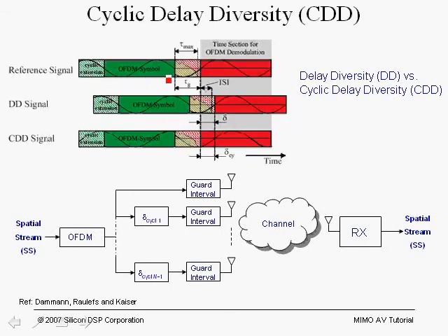Basically we're showing two OFDM symbols, one in green and one in red. In the case of OFDM we have the cyclic prefix, which in the case of 802.11a is 800 nanoseconds, or a copy of 16 samples at 20 megahertz of the OFDM symbol that is then prefixed to the OFDM symbol, forming a 4 microsecond symbol.